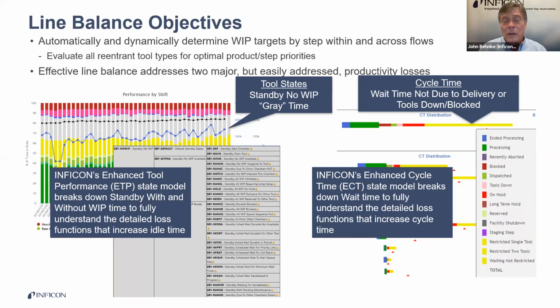Another benefit is that it reduces cycle time, because cycle time is predominantly queue time in any factory with X factor. By having an optimized linear line, the wait time is dropped exponentially because you don't have the large bubbles of inventory, which are sitting there sometimes for days, as opposed to a linear, well-distributed line. So you gain in both better utilization of your tools and, therefore, lower cycle time, which allows you to